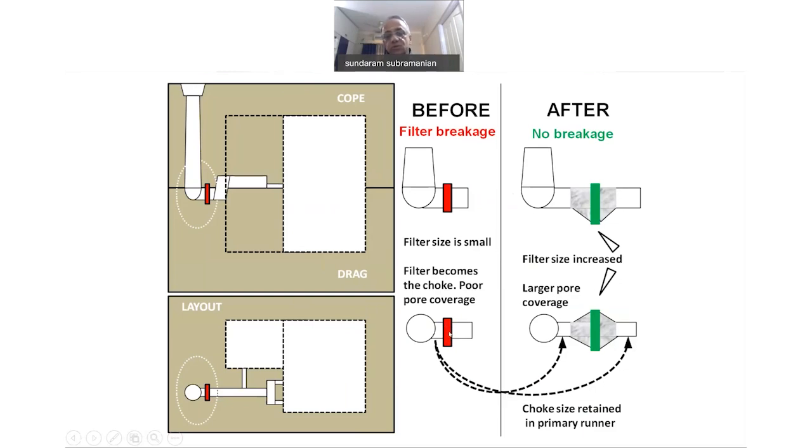Now, what is this choke? When there is a choke, there is a pressure buildup behind the filter. And then the velocity across the filter increases. These two adverse factors, with a higher temperature from the hot metal, over a period of a few seconds break the filter. The pieces of the filter are carried through the running system into the cast.